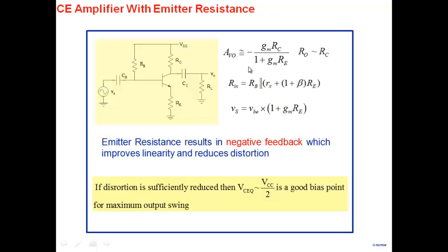So one of the strategies is, if you want a good amplifier, first of all, build up enough gain, and you don't have other things which are very nice. Let's say you're looking for an amplifier with a gain of 100, but with nice properties, other things, bandwidth and all that. So what you do is, you don't build an amplifier with a gain of 100. Build an amplifier with a gain of 1000. Multi-stage amplifier, build a gain of 1000. Then you apply negative feedback and sacrifice gain by a factor of 10.